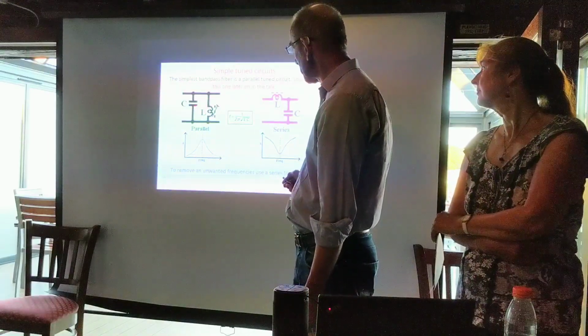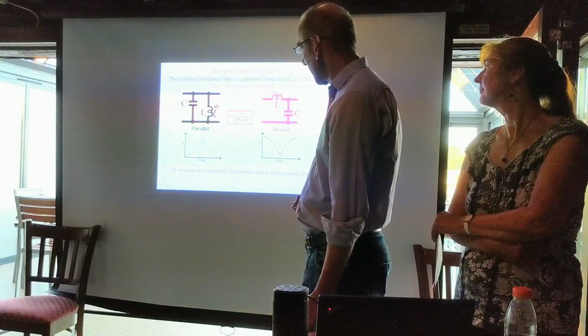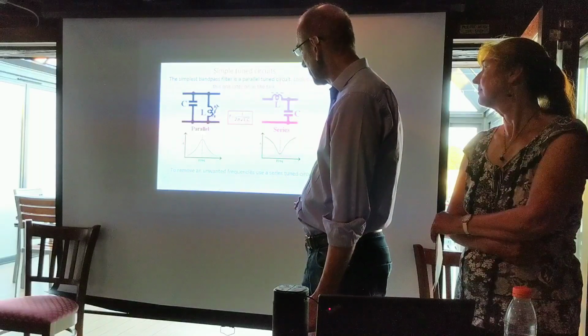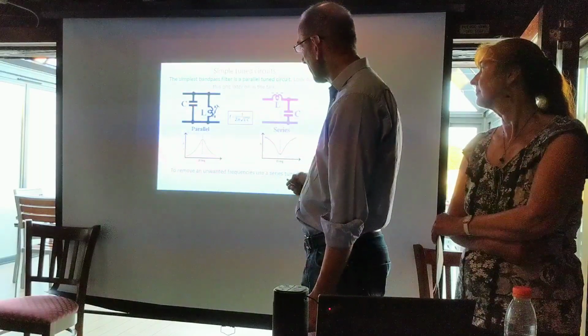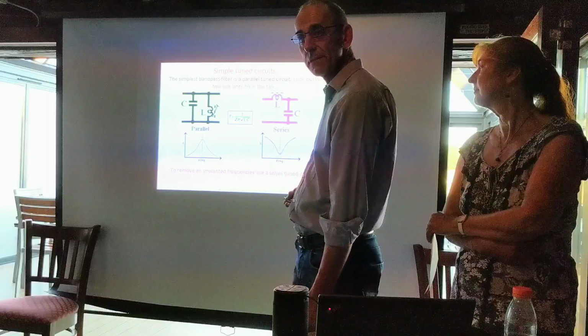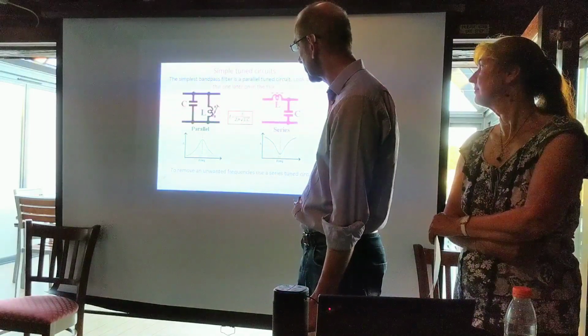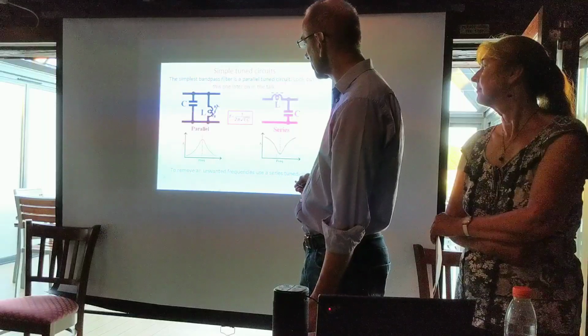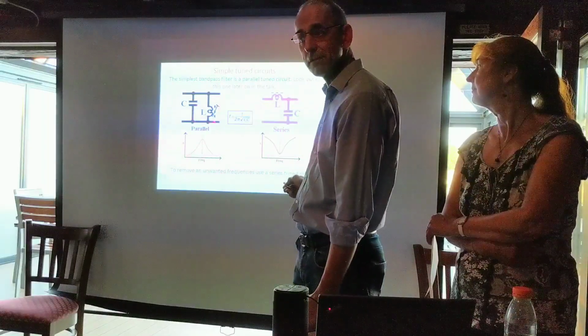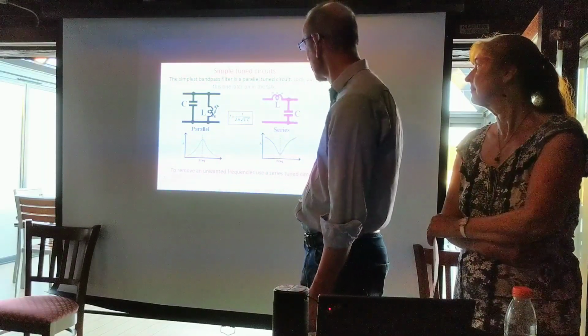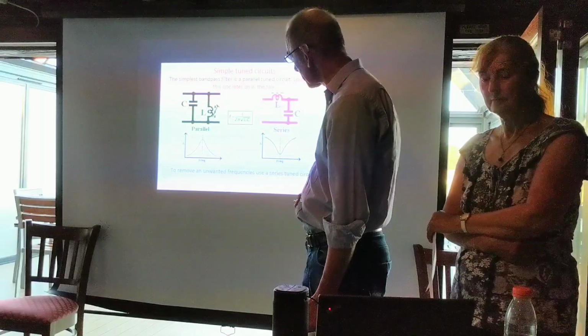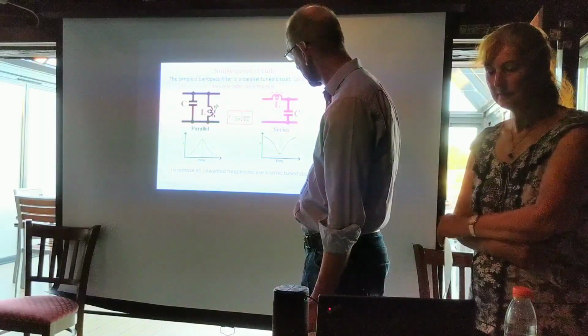Now this works a bit like a tuning fork, so at frequencies that are too low or too high, this looks like a short circuit, and therefore it attenuates any signals that are not at that resonant frequency. But at the resonant frequency, this all hums along beautifully, and you get a nice big output. So if you plot gain against frequency, you get a plot that looks like that.